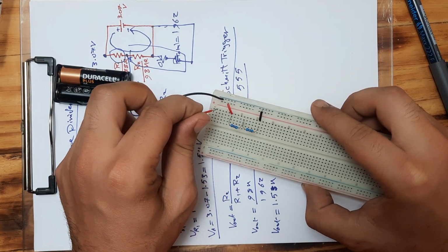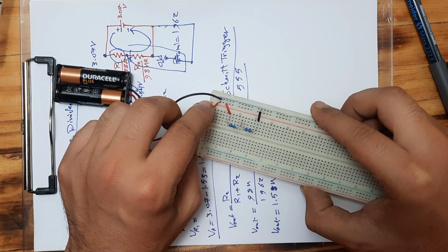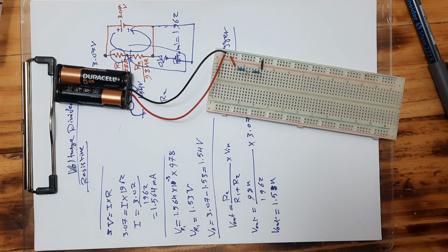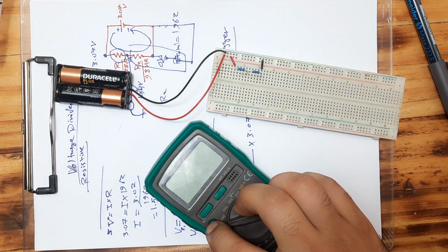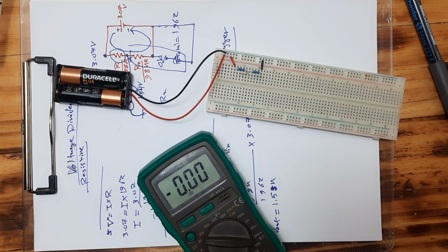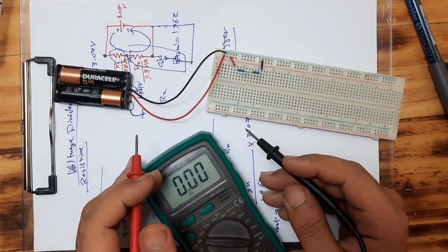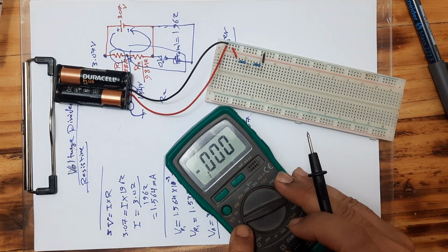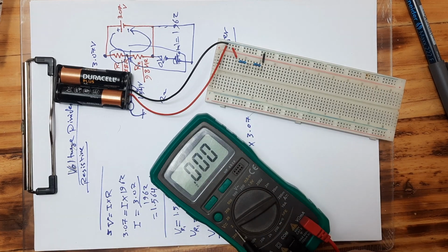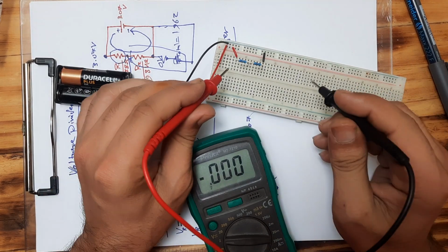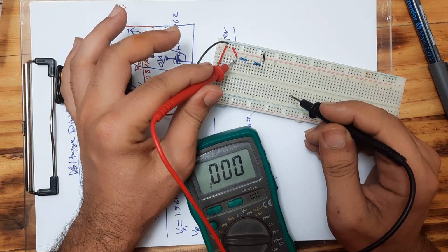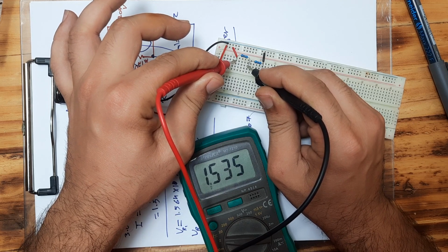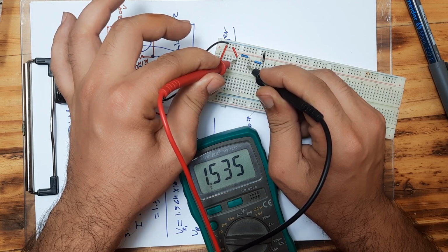So on my breadboard, I will power it, and now I want to take the multimeter and measure the voltage. This is R1, okay, this is R2. So first of all, I want to measure voltage, and since we know that the voltage will be below 2 volts, I would choose 2 here. Now this is V1, so I will see how much voltage we have here, and look what we have, 1.535, which is very, very close.